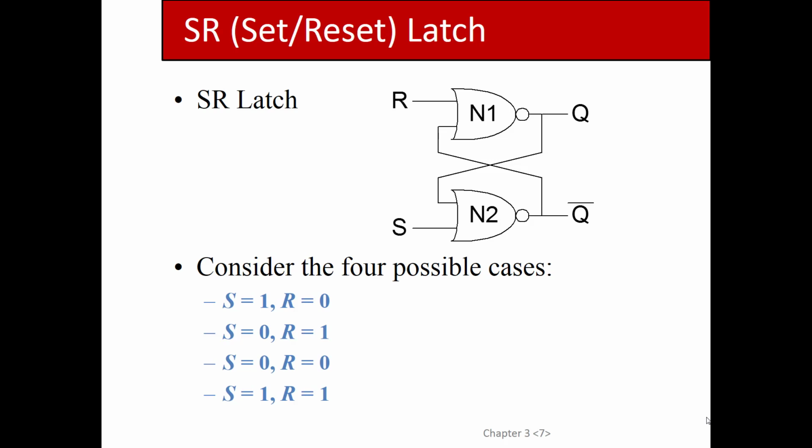If this guy is a 0, and you come into here, then this guy is going to be a 0, and then I would put a 0 for S. That way I'll have a 0 coming in here, a 1 coming out of here, a 0 going in here, and then I'll get a 1 and a 0. So I'll have a 0 coming out of here. So putting 1 for R and 0 for S assures that the output will be 1, 0.